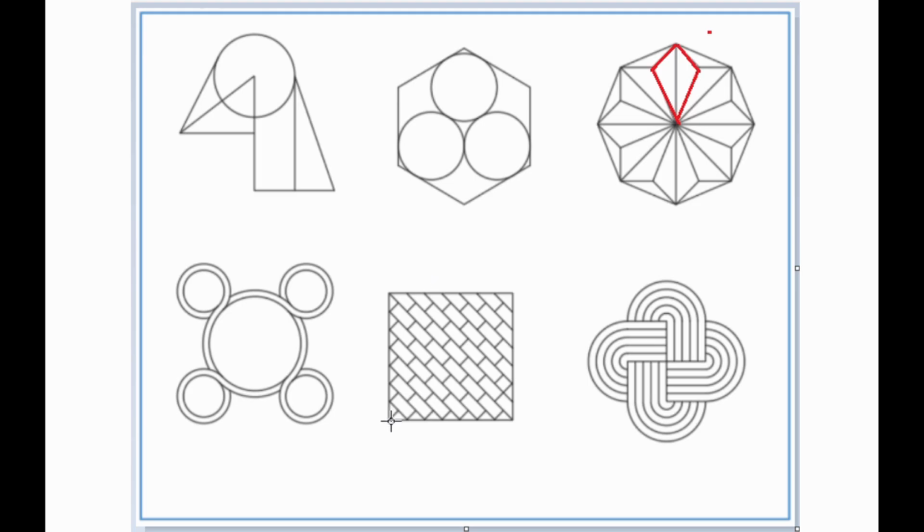because as we put a line in this part of the figure, we can see that this side of the figure perfectly reflects this side of the figure. Hence, the use of mirror is applicable. All we have to do is work on this side, and afterwards, when we are done, we can just apply the command MI or the mirror command.